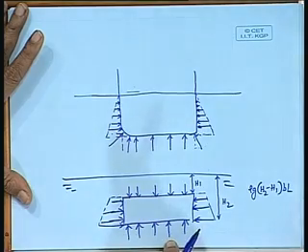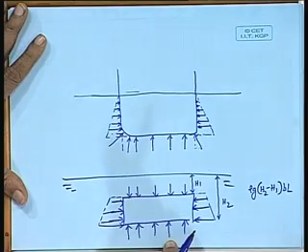Force is always upwards. You can see this is higher, is it not? So, if the body is in equilibrium in this condition, that means this upward force must be equal to buoyancy, equal to the weight of the body, which is acting downwards. Do you understand? That is what we call neutral equilibrium of a submerged body. That means left at any place, it will stay there.